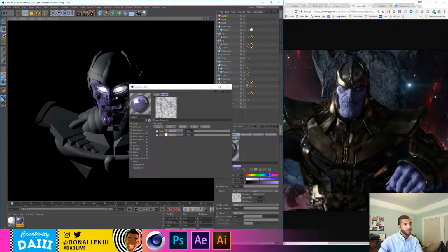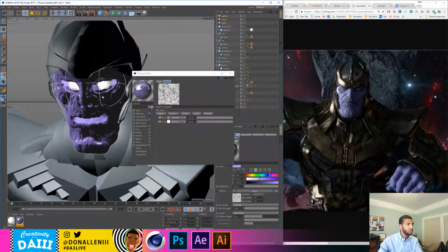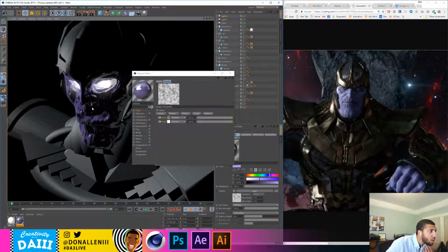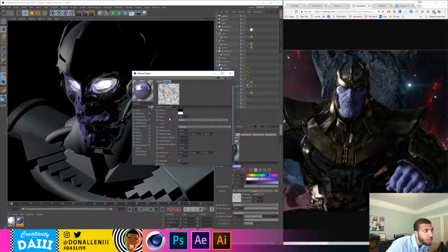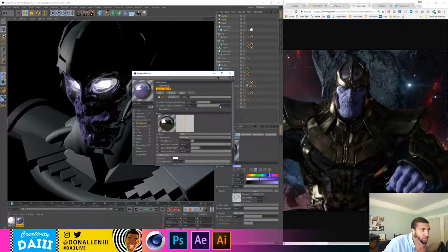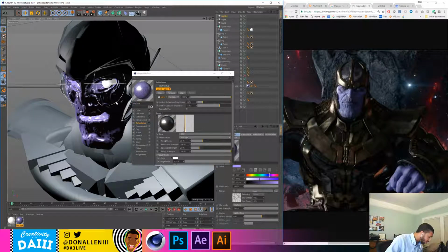All right, welcome back to Creativity with DA3 Live. We are in the sculpting, or sorry, the texturing part of Thanos, trying to make it cool. We're experimenting with different textures now just to see what we can get. Let's go to that reflection channel and actually reduce the reflection strength. It's a little bit too strong. Maybe roughen the skin up a little bit so that the light scatters more when the light hits against the alien's face.